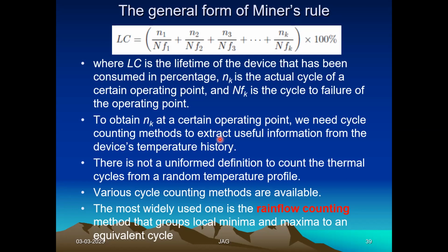Similarly, when you come down, ramp down, the mechanical energy will be in excess. Don't use any electrical energy. Instead, it can generate electrical energy, regenerative braking. Then the stress associated with the electrical components is totally different. Understood? So this is called the road profile.